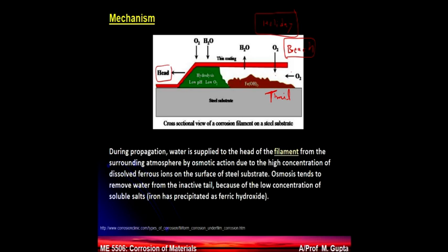It's a technical term. So when it goes inside, this coating is pretty good. It's not cracking off. So if you use a brittle coating, and this kind of corrosion sets in and wants to move, it will crack here. It will get damaged. So if it gets damaged, then oxygen will come from here.